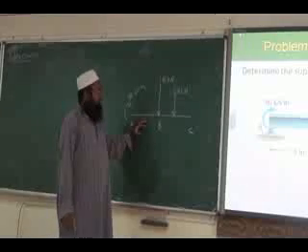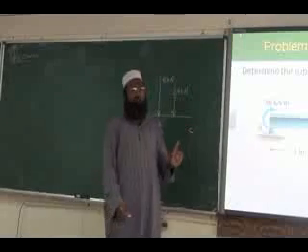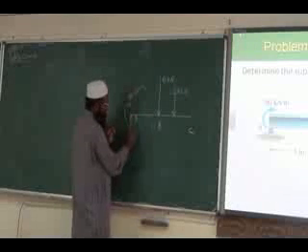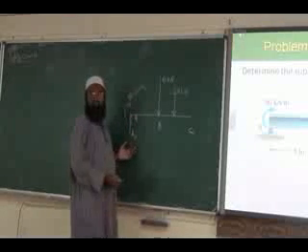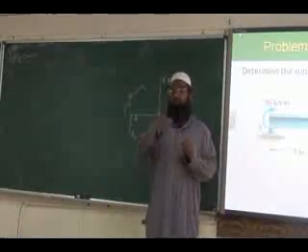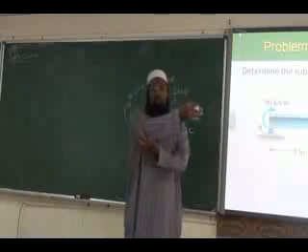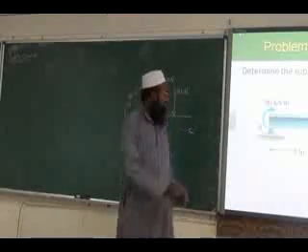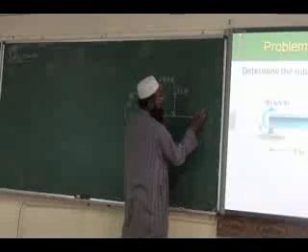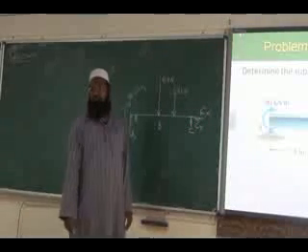Now point A is simply supported. A roller is there, so you will have only one reaction acting vertically like this. So you represent this as AY. One support reaction. Similarly, point C has a hinged support. It can rotate. The beam can rotate like this, hinged. It cannot translate in y direction as well as x direction. So you have two reactions, CX and CY. Okay, two reactions.